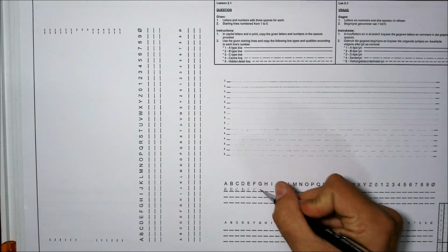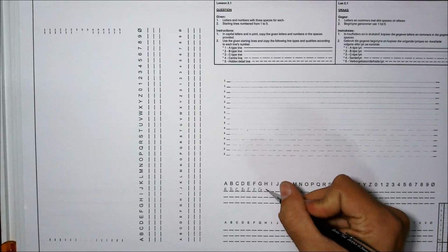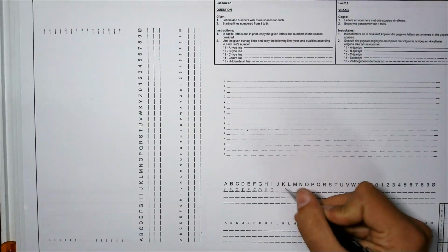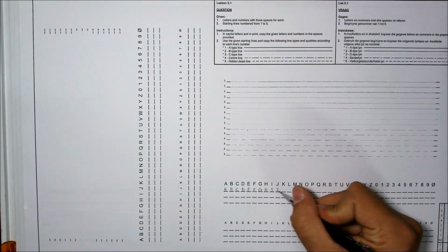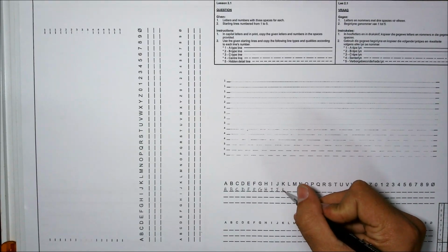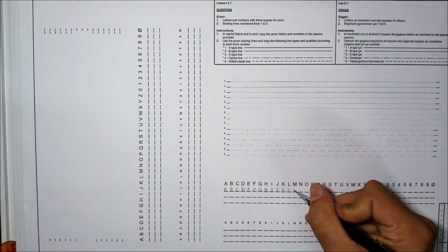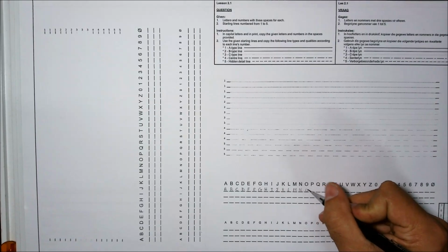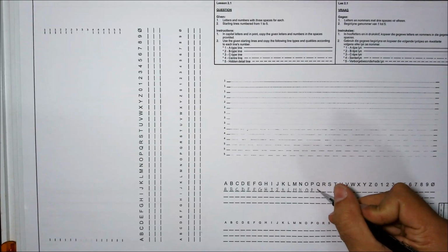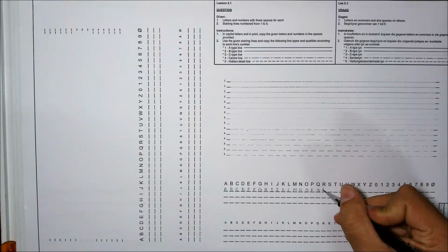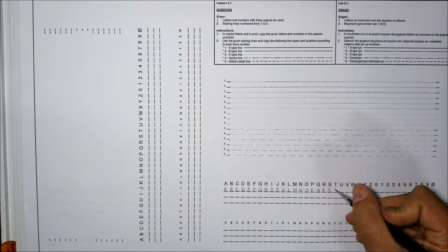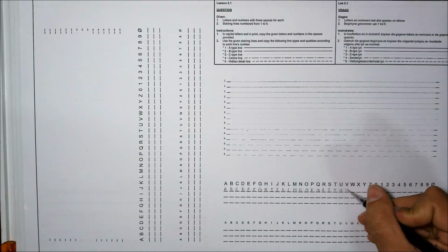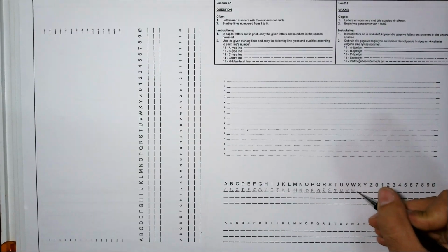And you can see I'm kind of now rushing through this. But when you do this, really try and, because it's going to be your very first time looking at this EGD and the writing, all of you have written capital letters somewhere in your life. But every single thing that you are going to do in EGD has to be labeled in capital letters. So try and take your time, get the feel for this, get the feel for the letter size, and see if you can get everything roughly the same.